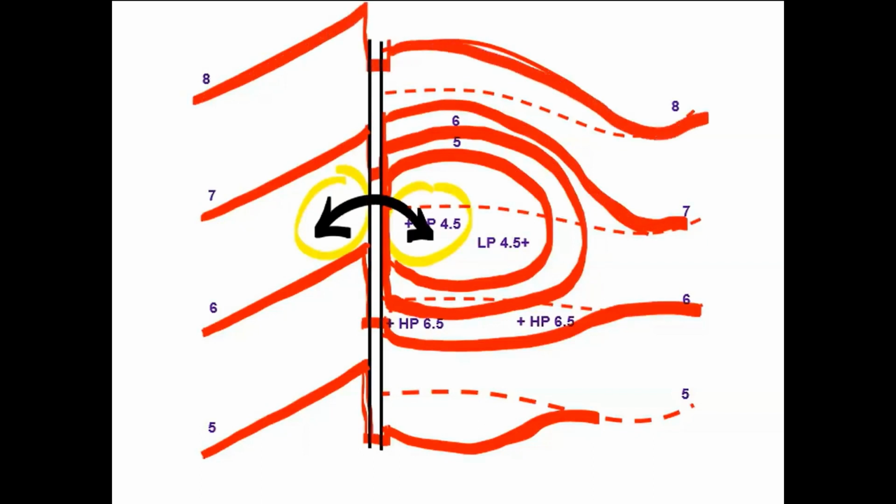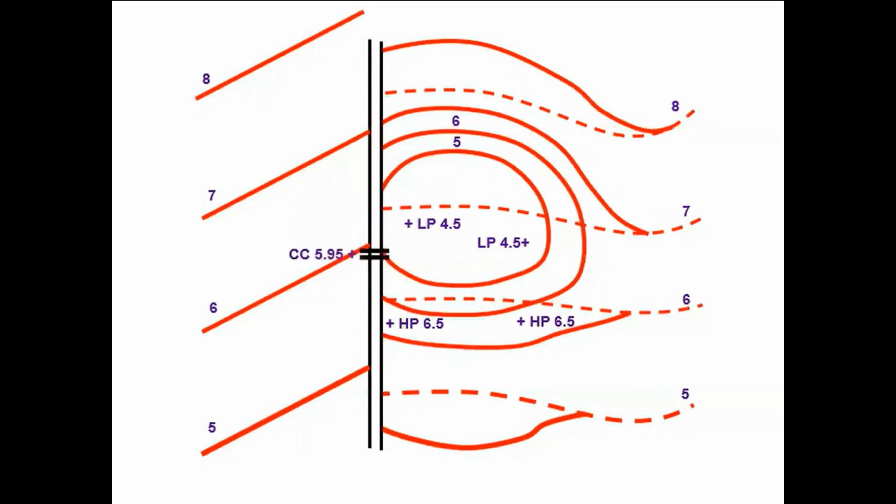This is a slide you should probably come back to a few times to make sure that you understand how we're able to run these contours along the back side of that curb in order to get the depth that you need to hold the water in your landscape area. So now we've added a curb cut here, abbreviation CC. It's not a standard in the profession yet, but it's what we'll be using for this class.